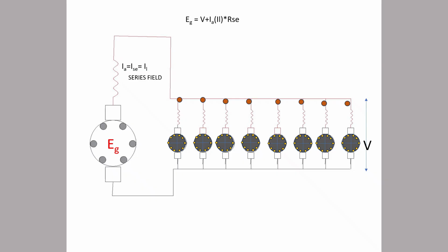So, in our old electric locomotives, we were using DC series motor. Why DC series motor? Because it has good starting torque. When the train is stalled, to start it needs power, more starting torque. So to start from stall, we better use a DC series motor in the electric locomotive. It will be helpful.